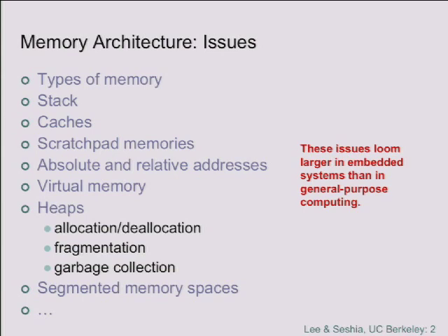What are the trade-offs in using these memories? Why don't we just use flash memory for everything, and then we don't have to worry about volatility? Yeah. It's slower. Yeah, that's a problem. What else? Yeah, most of the technologies actually have a limited number of writes to them. In today's technologies, it's on the order of 10,000. For each memory location, you can update it 10,000 times, and then it's kaput. Can't use it anymore. Okay?